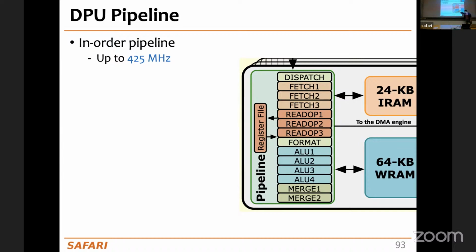The processor, this small core, this DPU, can access data that resides here in the DRAM bank, right? The way of accessing data in the DRAM bank is, first of all, asking this DMA engine to move data from the DRAM to this WRAM, that is a sort of a cache, but it's not really a cache because it's not hardware managed. It's managed by the programmer. So the programmer has to tell the DMA engine when to bring data from the DRAM to the WRAM,